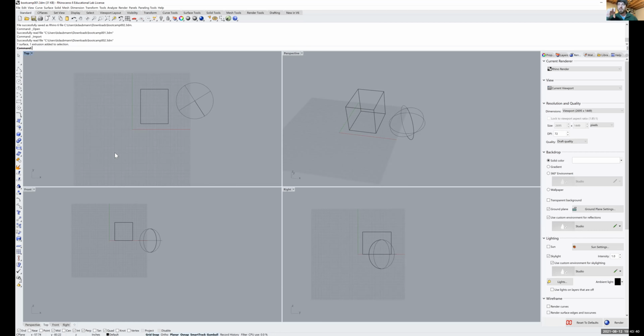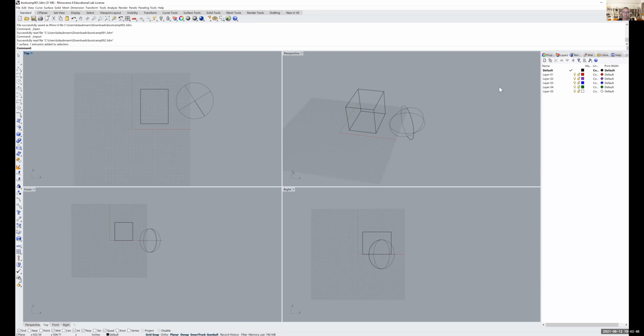And what you might do, and maybe I'll answer your question in a very different way, is maybe that shouldn't happen, in the best case. What I would say is that the origin, you can typically do 0,0,0, which will give you the origin where X, Y, and Z are all 0. There's also shorthand in Rhino, which is just 0. When you just type 0 and enter, it'll put it at the origin.